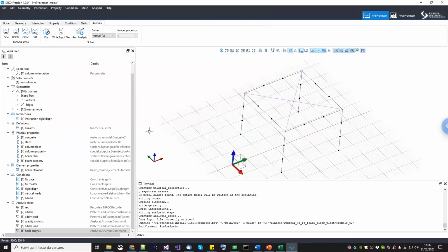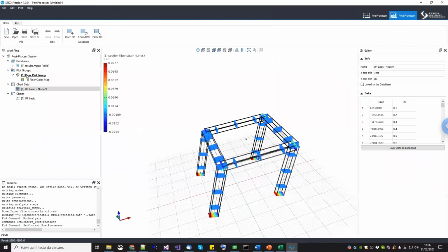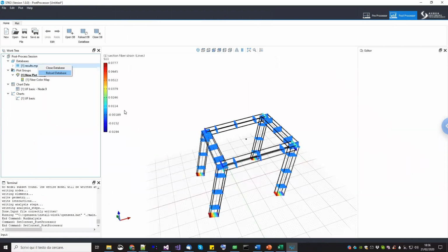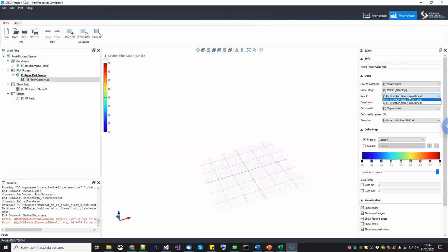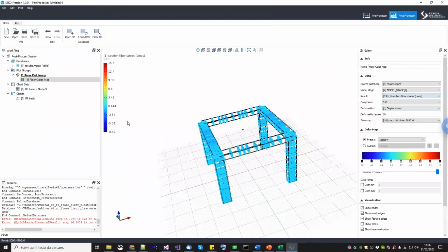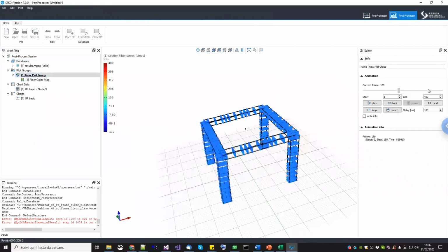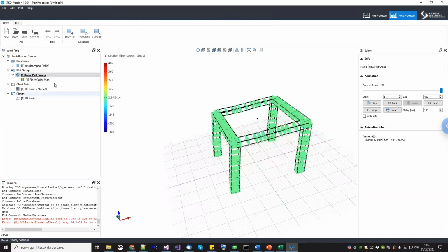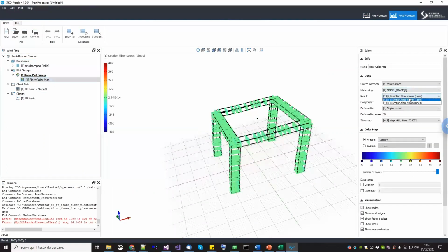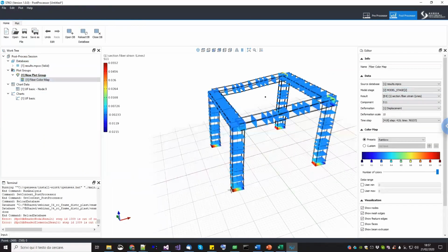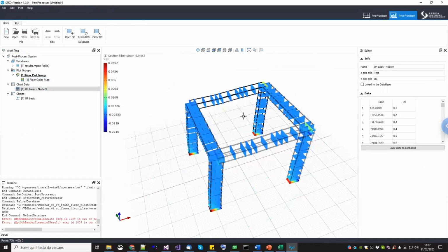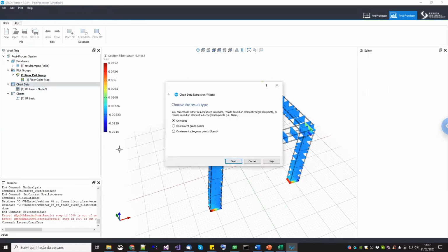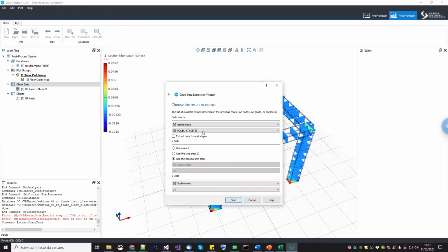Okay, perfect. Now we go back to the post-processor, we reload it. Okay, now we can go just here, we change. Okay, let's see what's going on. When it is starting localizing, let me go back to the strain rather than the stress. There is a convergence problem. So let's go here and plot the same load displacement curve on this discretized model, and let's see what happens. You would actually expect to obtain the same result, but you're not going to obtain the same result.